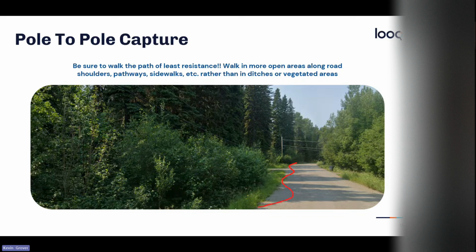Make sure you're walking down road shoulders, pathways, sidewalks, that kind of thing, rather than walking directly in the ditches or trucking through heavily vegetated areas. The benefit of this is you're able to see it. We can reconstruct better. We'll have better GNSS data in this example as well, we'll just have better GPS coverage. The precision is going to be a little bit better. And we can also see more information from the side.